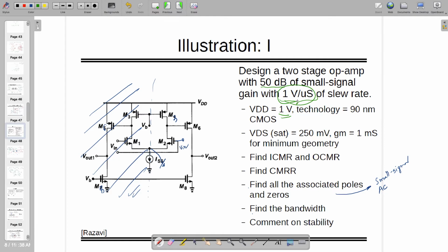I'm telling you, if you want 1 megahertz of bandwidth, and you are achieving 0.5 megahertz, or I should say that 1 megahertz is already there, but phase margin is equal to 0 degree or something less than 45 degree, then for tuning it, you have to increase the current. So that the second pole will be outside UGBW, and definitely bandwidth will increase to maybe some other number.